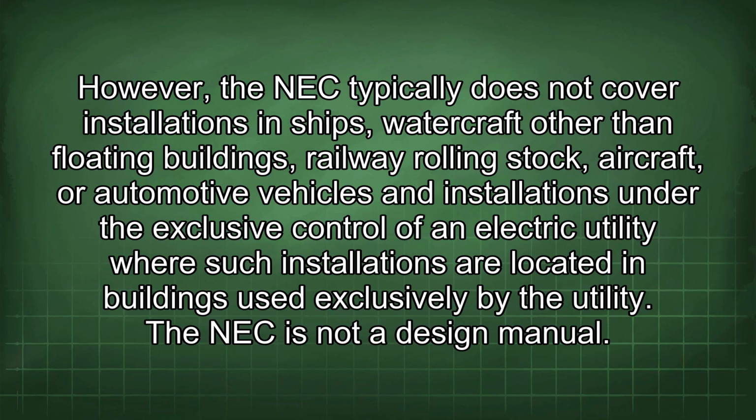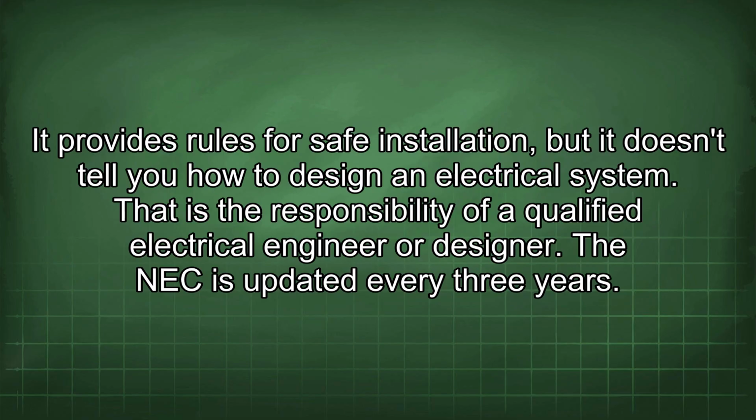However, the NEC typically does not cover installations in ships, watercraft other than floating buildings, railway rolling stock, aircraft, or automotive vehicles, and installations under the exclusive control of an electric utility where such installations are located in buildings used exclusively by the utility. The NEC is not a design manual. It provides rules for safe installation, but it doesn't tell you how to design an electrical system. That is the responsibility of a qualified electrical engineer or designer.